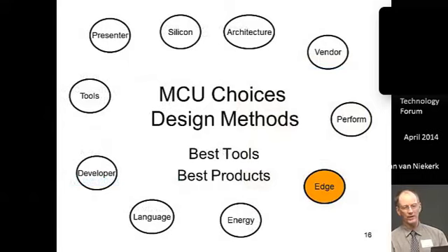Another performance point that I want to make is when you design a microcontroller, the question is how much spare processing power should you have in it? You can go read about it a little bit on the internet, it's called CPU utilization. Your microcontroller should not be busier than about 70% of the time if you're doing typical scheduling in a microcontroller. So don't go design your embedded system where the microcontroller is 99.99% busy, because you're going to run into trouble.